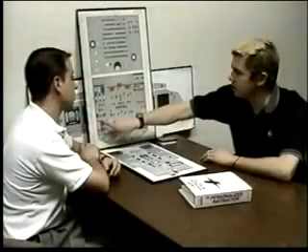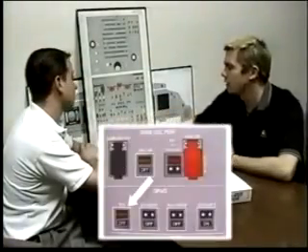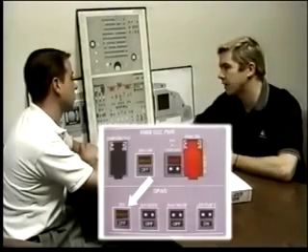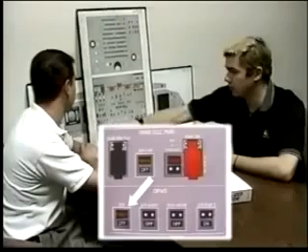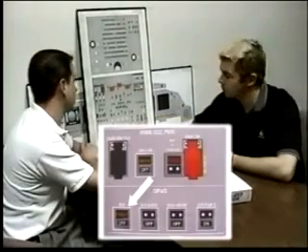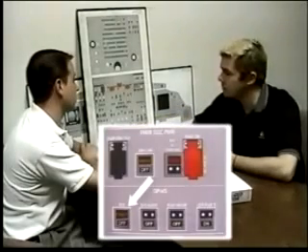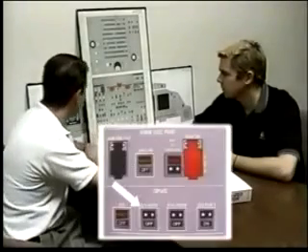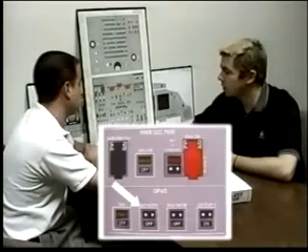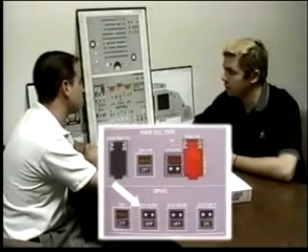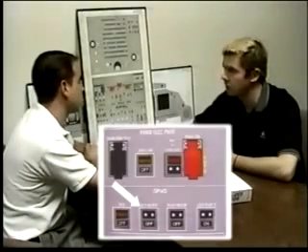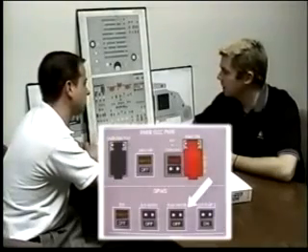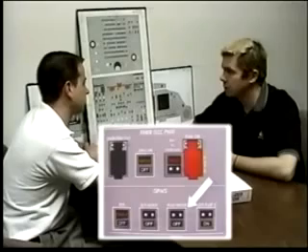If I select the GPWS system switch off, then that will deactivate GPWS, but it does not affect eGPWS. By selecting the system off, or even if I have a fault, I don't get any modes of GPWS at all. When would you select glide slope mode to off? If I were flying a localizer approach to a runway that had an ILS where the ILS was either out of service or unreliable. What about the flap mode to off? Anytime I was landing in an abnormal flap configuration, I'd select that off.